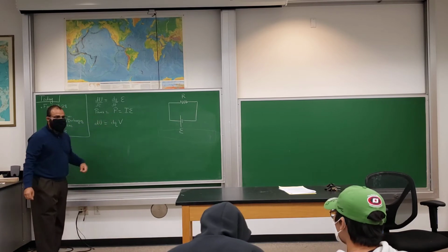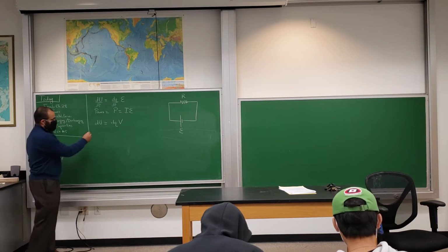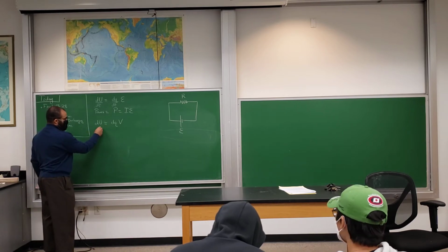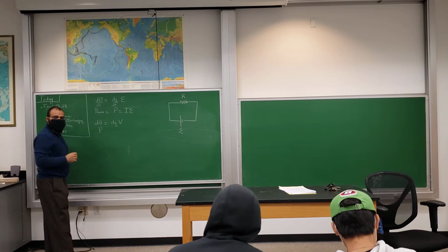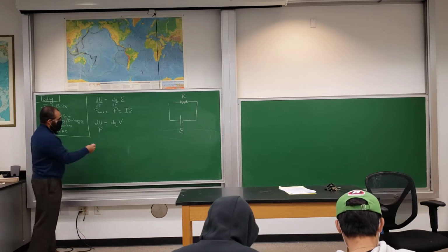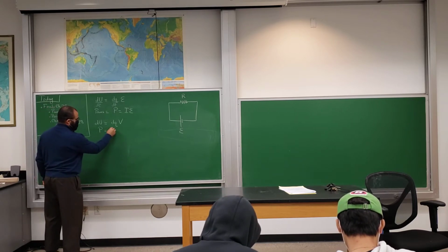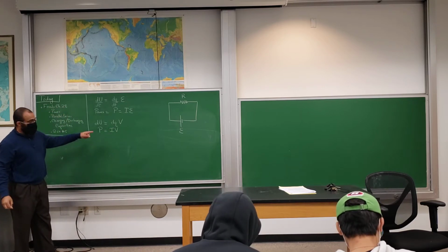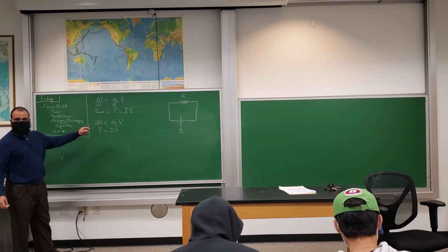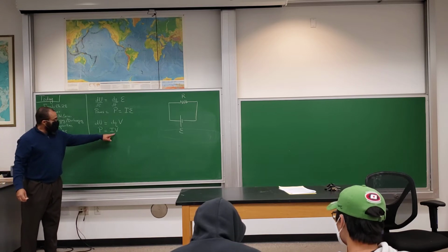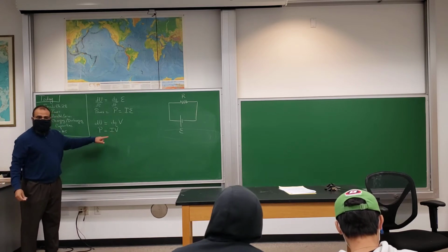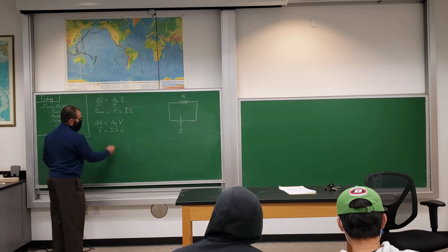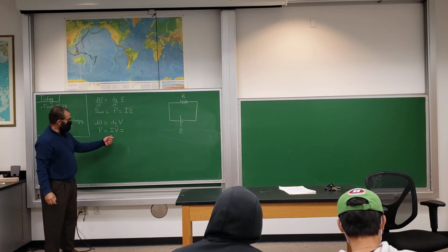So how much thermal energy is there? We'll divide both sides by dt again. And so you get the power, or the energy given off as thermal, as heat, would be dq/dt, which is I times the voltage. So that's the power dissipated in the resistor. This is not the most common formula. Usually you see it this way. I'll give you two other forms.